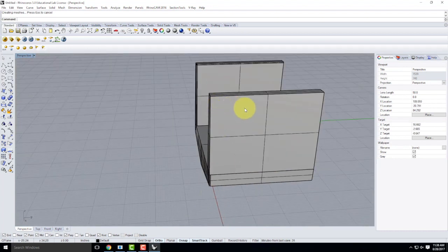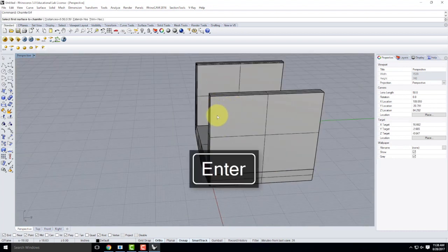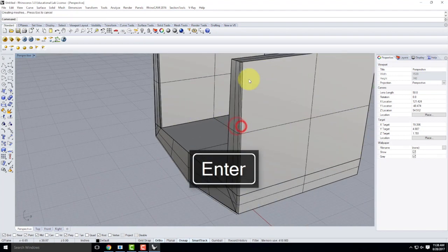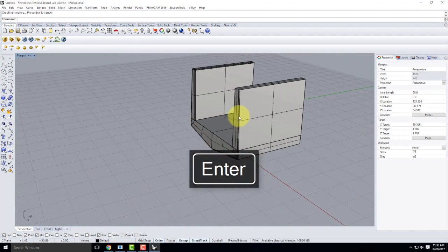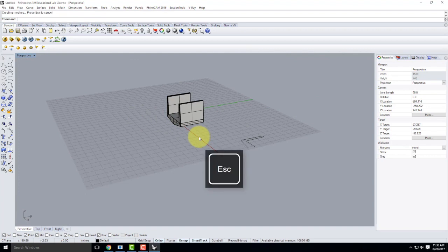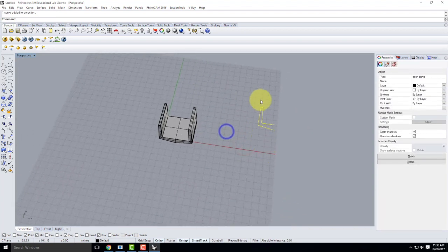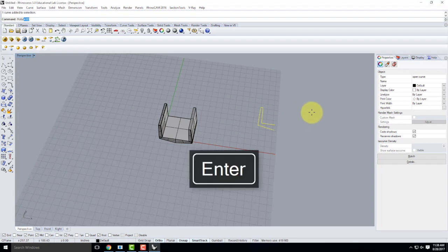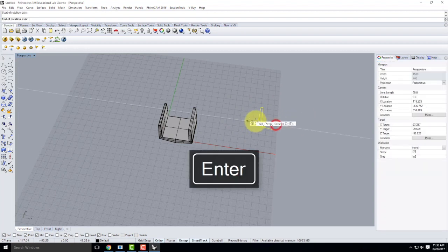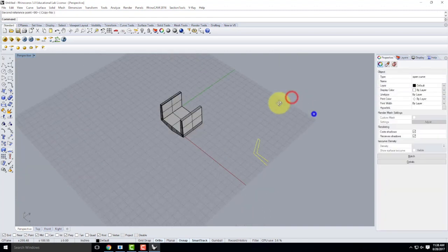So then I'll continue the rest of the way up here, chamfer surface, and I'll work my way up the rest of the object. Okay? Now, I told you earlier that if I were modeling this, I'd use some tricks. And if I were using tricks, essentially what I'd do is I'd draw this half of a shape. I'd rotate 3D on that half of a shape. I'd flip it up.